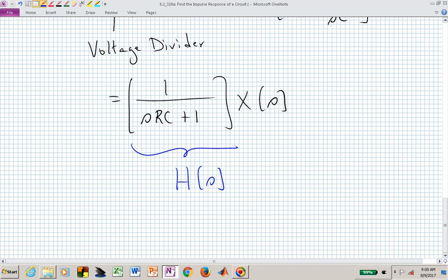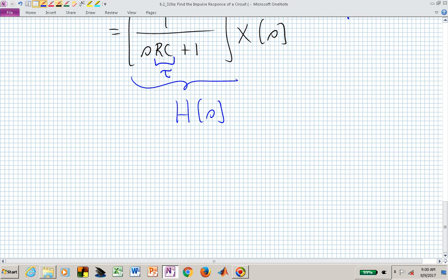So our transfer function now, and this particular transfer function is written in a special form, and that's this time constant form, where the time constant tau is RC, the RC product. In order to find what we want, we probably want to go ahead and think about this transfer function in a different representation, but we can now say that H of S is either 1 over S RC plus 1, or we could factor out the RC.